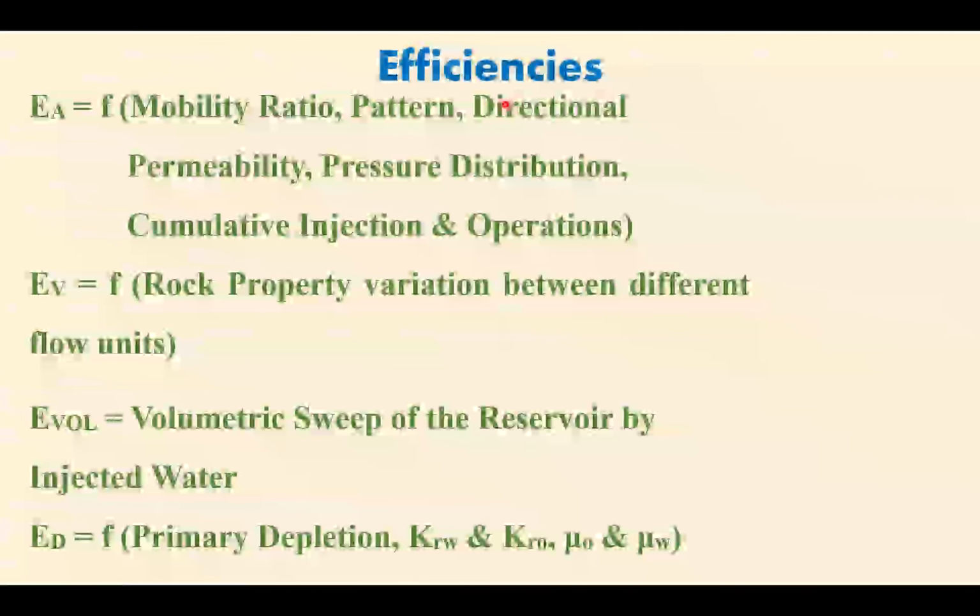So the injectivity issue of the different chemicals is a major problem. Then pressure distribution and cumulative injection. So injectivity is a very important parameter. Considering the very ultra low permeability, we have to take care of the injectivity, and of how this injected fluid covers all this area, that is, to increase the sweep efficiency.